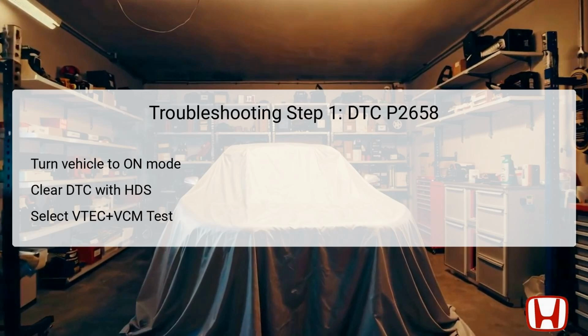After clearing, the technician should select the VTEC plus Variable Cylinder Management VCM test in the HDS. This function is specifically designed to check the operational status of VTEC and related components, including the solenoid. Finally, the technician must check for any pending or confirmed DTCs with the HDS to determine if the P2658 code reappears. If it does, it indicates that the initial issue still persists and further investigation is warranted.